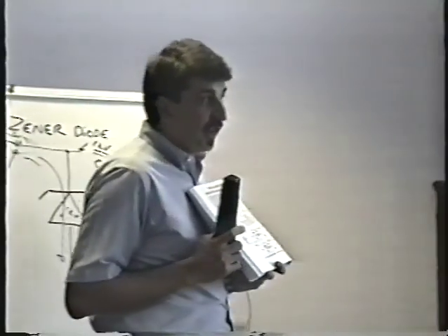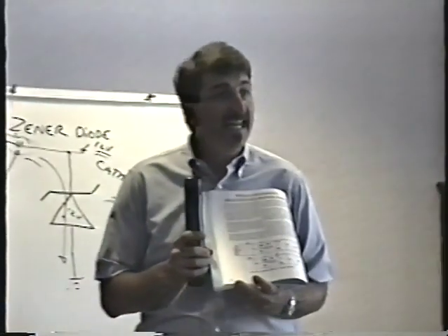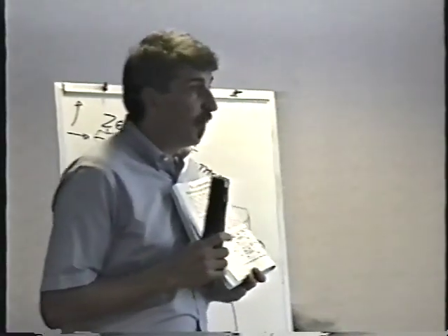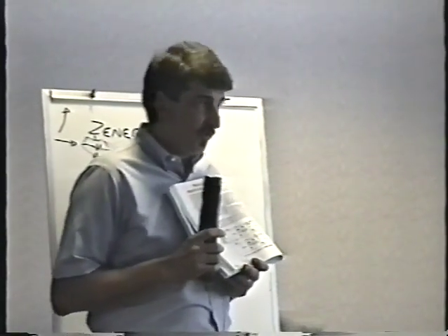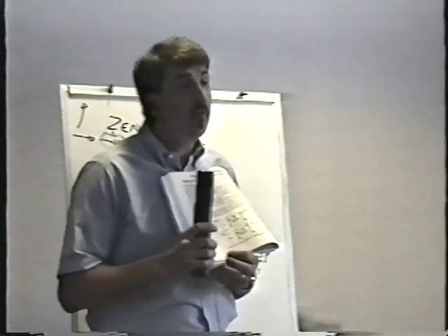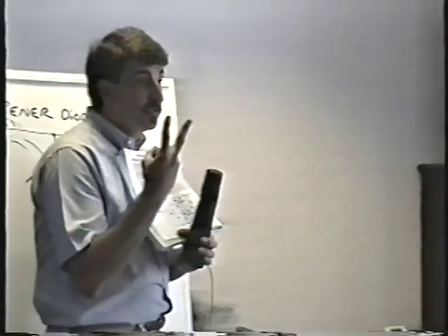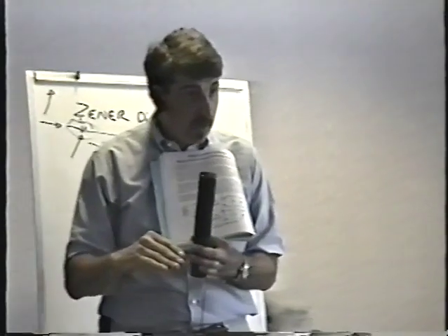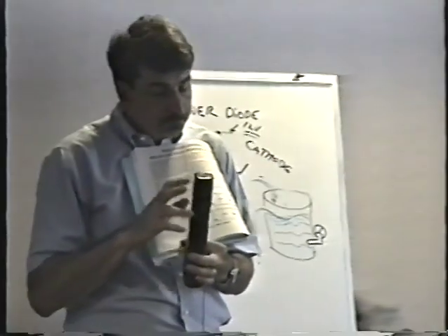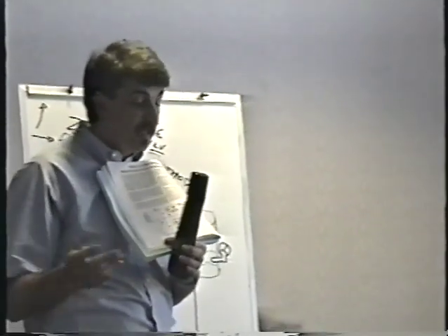On page 32, this is the Williams high voltage power supply. This is the power supply that powers the score displays in a Williams pinball. The score displays in a pinball are not LEDs. A lot of people think they are, but they're not. They're neon gas discharge display tubes. They take 200 volts to operate. To get that 200 volts, they make two different power supplies. One is plus 100 volts, the other one is minus 100 volts. The difference between plus 100 and minus 100 is 200 volts.